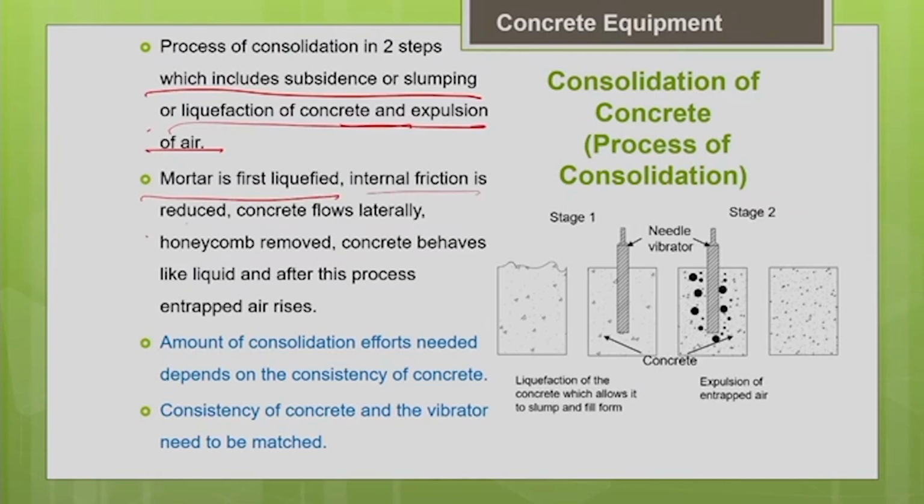The internal friction is reduced because of the vibration, and the concrete starts flowing laterally. Any honeycomb in the concrete will be easily removed. As I told you, the concrete behaves like a liquid and fills the formwork. After this process, you can see that the air will rise to the top. Your entrapped air will rise to the top surface of the concrete. You can see this in the picture also.